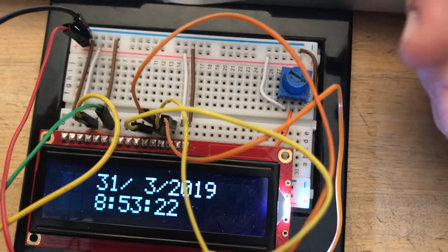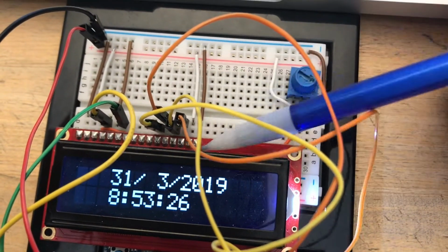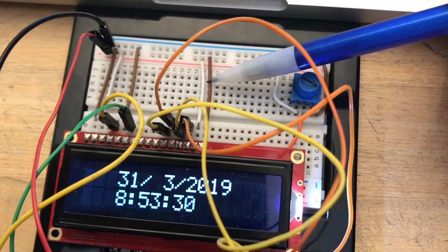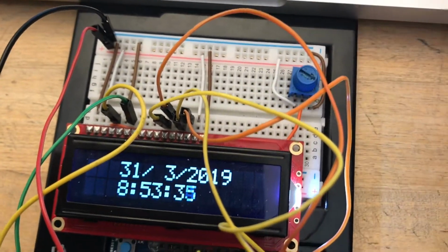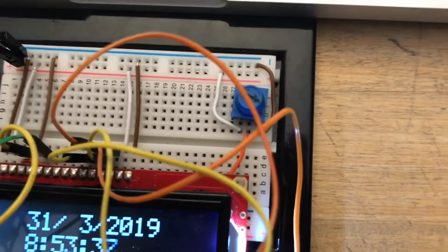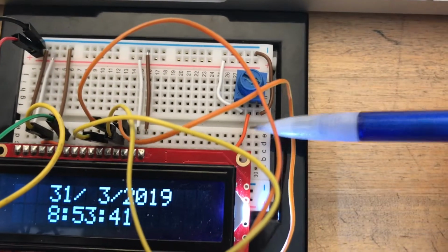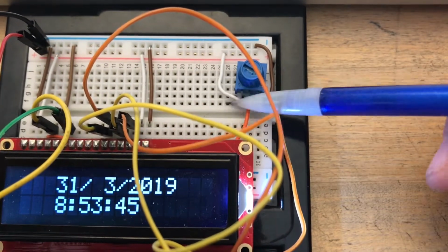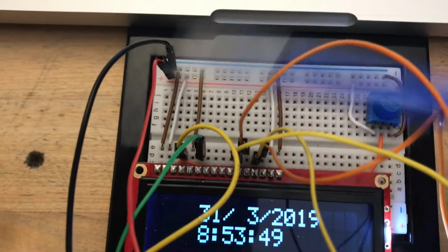And then here, this white wire is going to connect to the 3.3 volts, and it's the backlight positive pin, and this brown wire here is the backlight negative pin, and it's going to connect to the negative column of the ground. Then we get to the potentiometer. It is connected to the LCD screen through this orange cable like we said before. It is grounded by this brown wire here, and it connects to power through this white wire to the 3.3 volts.